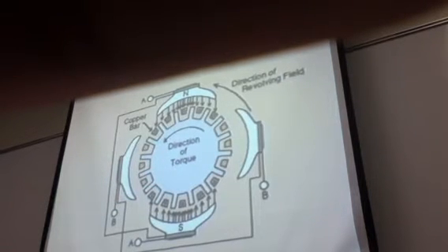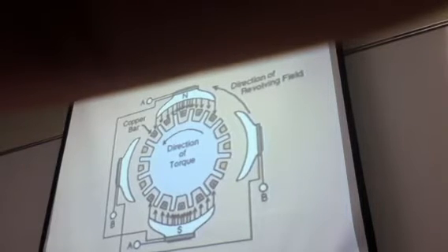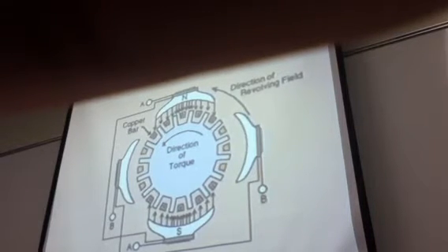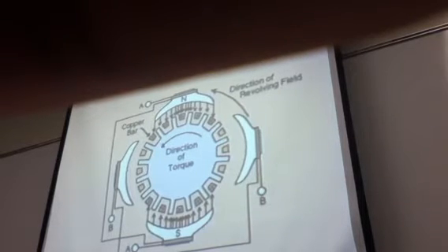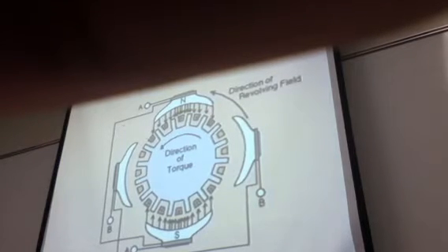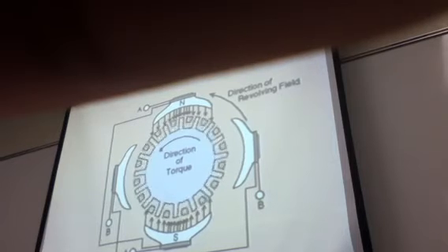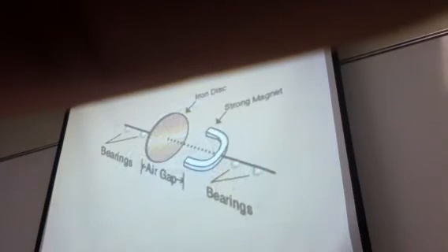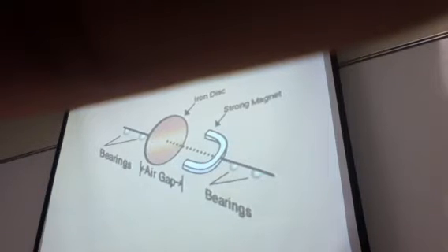We discussed magnetic induction in Module 2. In a motor, the powerful magnetic field created by the stator induces a current in the copper conductors attached to the rotor. This current creates its own magnetic field. The principle of magnetic attraction and repulsion then takes over and causes the rotor to turn. Let's explore in more detail how the motor actually works.